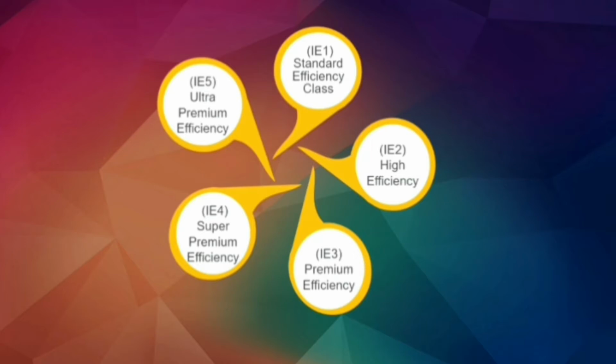Okay, for this time, there are 7 requirements that we emphasize to determine the classes of each motor. First, power output, second, poles, third, speed, fourth, RPM frequency, fifth, temperature class, sixth, insulation class, and lastly protection technology. For the power output, IE1 until IE3 give the same output power, which is 0.75 kilowatt until 355 kilowatt. Except for the IE4, it produces 2.2 kilowatt until 230 kilowatt.